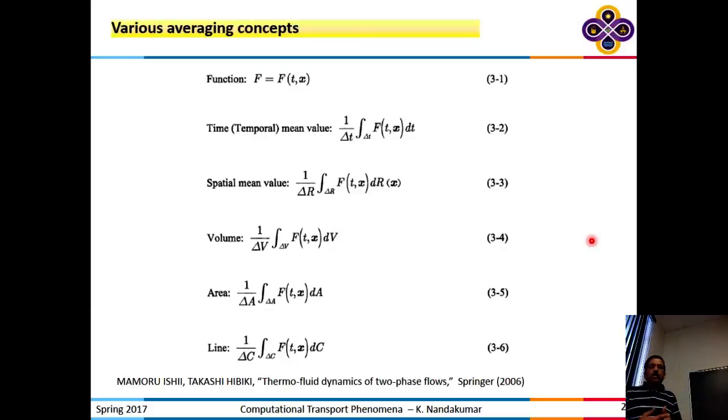So now we are going to talk about the averaging concept, because we know what the velocity field looks like. For turbulent flow, the velocity at a particular point, as a function of time, is going to look something like this. Very random. So I can find the average value and ask the question, how does the average value change from point to point in a pipe? Okay, and that's what I showed you in the profile. It looks much flatter. Then these fluctuations are there, right? And the fluctuations are going to be purely random. And so I need to build statistically meaningful interpretations of it.